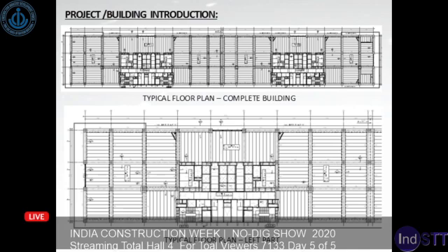We can see on the lower half the left part of the building, and the arrangement is typically a hollow core slab as a floor system, with beams on the perimeter and in one direction in the middle supporting these hollow core slabs, columns supporting the beams, walls, and the central area, which is basically the central core and lobby, lift lobby, staircases, etc.